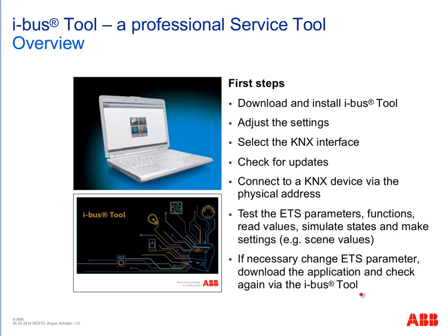So how to work with this new IBUS tool? Here are the first steps: download and install the IBUS tool. In the next slides I explain it step by step. Adjust your settings, your language for example, then your KNX interface via USB or IP. Check if there are updates available for the IBUS tool. Connect via the physical or individual address to a KNX device.